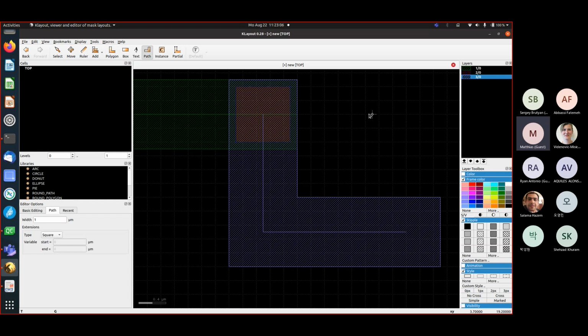Typically, you have design rules. So you cannot draw any kind of via, but typically you have a very specific size you can draw. And maybe it's like 100 by 100 nanometer, something like that. I think in Skywater it's like 150. So you draw a single square to form this via. And of course the metal wires also have design rules. So you cannot go below a certain width. Often you can even not go above a certain width. So typically there's a standard width you're going to use for routing, for metal layers.